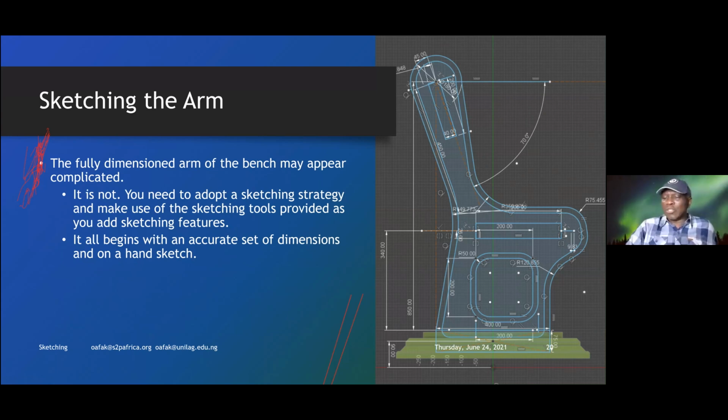What I'm going to do is to let you first of all see that if you look at this drawing, you will see that the top here is a circular rounding. And that circle is located at the point which is exactly vertically related to this point here. So we're going to do this drawing by using this distance and the fact that this thing is right on top. Let us see what it is. It is a circle of 180 millimeters. That's a circle of 180 millimeters there. And the center is located at 850 from this point.